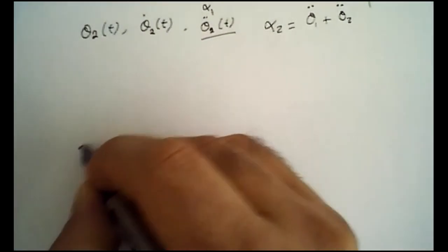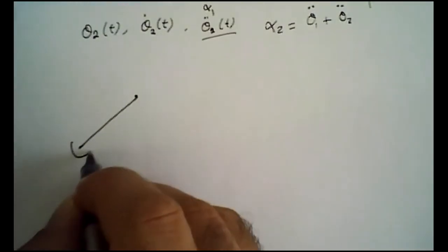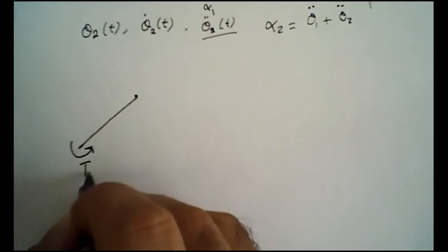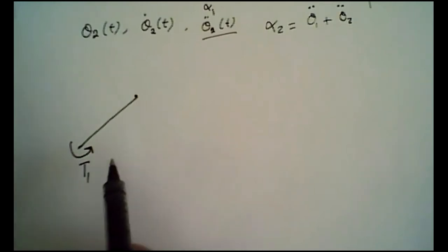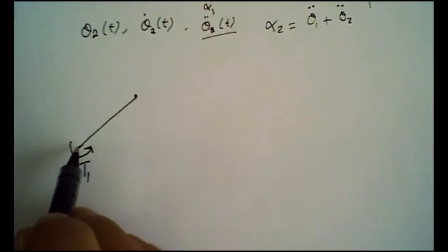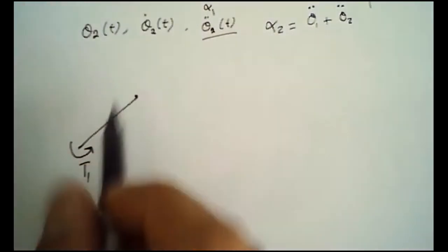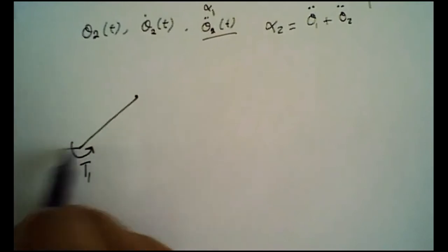On the first link, what are the forces on the first link? Well, we have a motor that is trying to push it with some torque. Here I'm assuming the torque is like that, right? Ultimately, if I solve for T1 and the value of T1 is minus 0.5 or minus 2, then it would be the opposite of what I've assumed. And if the final value of T1 is positive, it means that my guess was actually right. And so this is the first unknown, and then obviously this is hinged, or the motor basically has to be fixed. So you actually have some forces here, right?